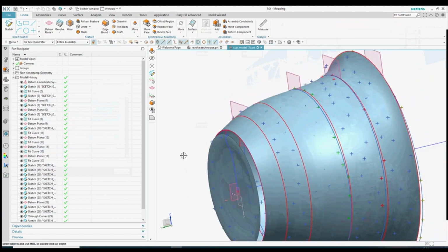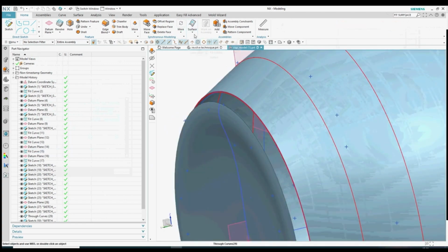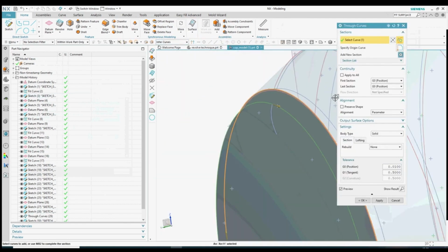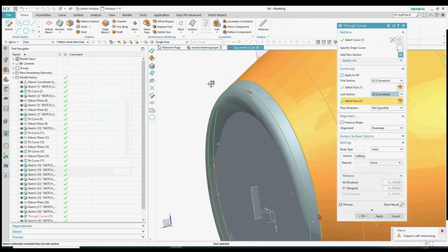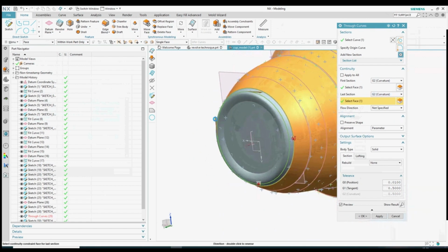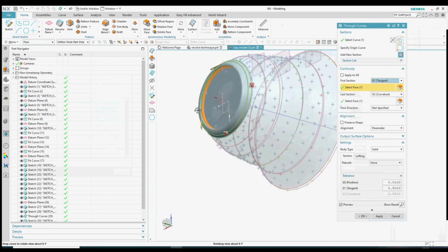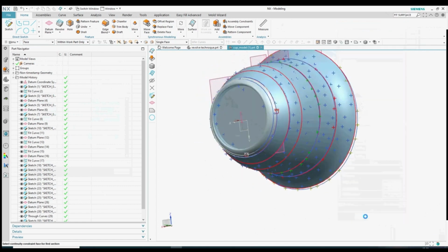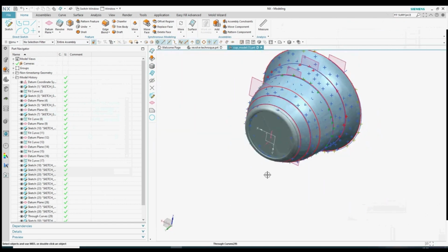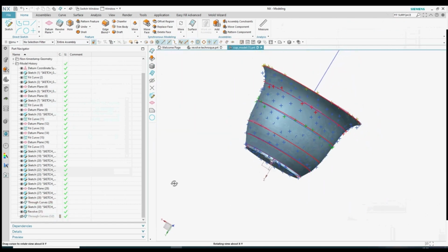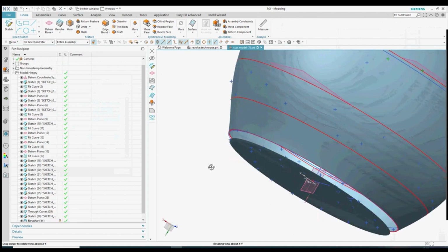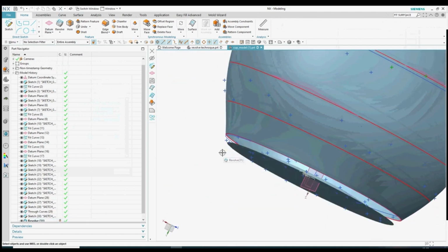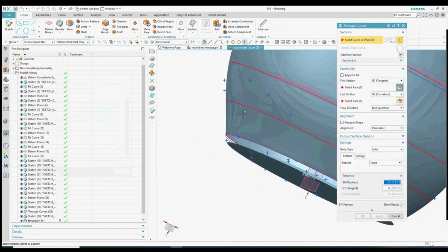Great. So now I'm going to use the through curves option, and I'm going to bridge the two surfaces. When we are bridging, we would like to have G2 or G3 curvatures. However, because of the shape of the model, this is not always possible. And if we try to force the software to do it, it will give me undesired results, just like this odd shape right here. Now, I don't want that bump in the end. Therefore, I'm going to compromise and set one of the surfaces to G1.